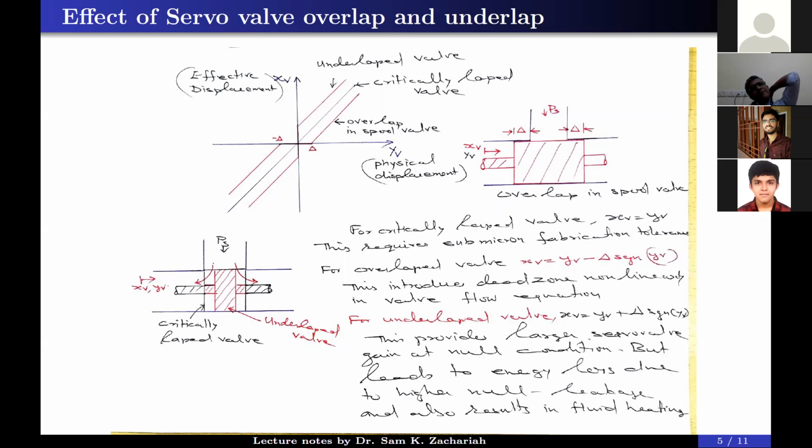And you have studied in control system the effect of gain on system dynamic characteristics. Here, what will happen is the closed loop bandwidth will come down for low amplitude. That is the issue. If the closed loop bandwidth of the actuator comes down, it will interact with the autopilot dynamics. So there will be an unhealthy interaction between the digital autopilot and actuator, which will lead to loss of stability for the autopilot, and it will affect the vehicle stability. So even though you may think it's insignificant, it is not like that. It is a very, very important part of the overall system.